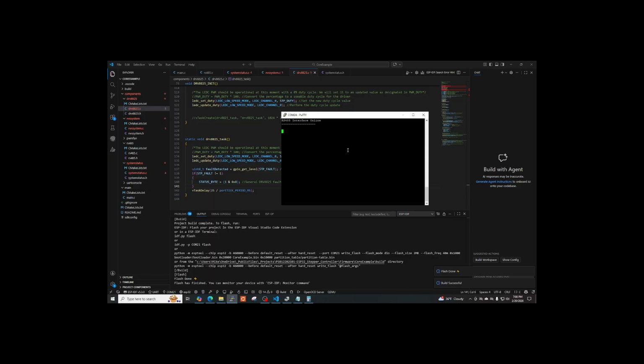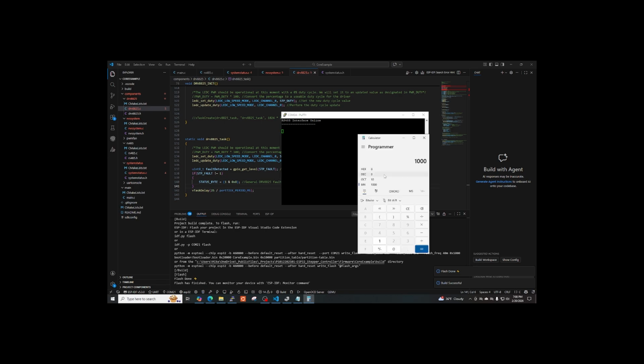Okay, well, so we've got that. So if just the stepper motor driver faults, the decimal value returned would be 8, and the hex value would be 0x8. And then basically, if multiple systems are faulting out, it would be a combination of all of these. So hopefully,